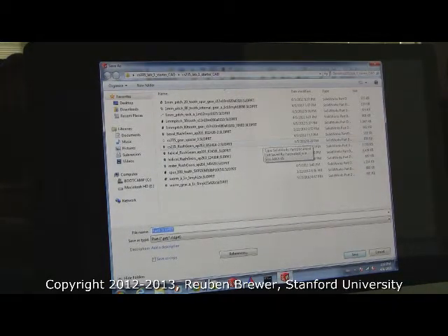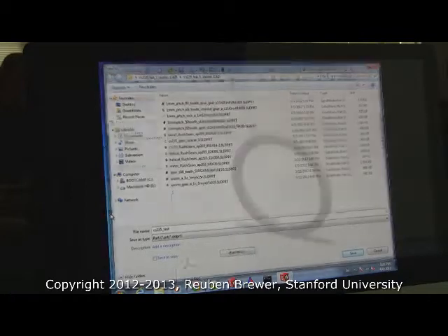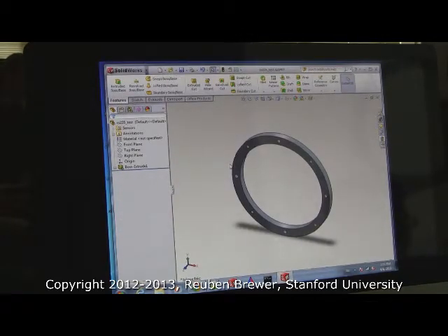Now it's very important. SolidWorks, for some reason, tries to save things in squirrely positions, like the temp files of Internet Explorer. I don't know why. Always make sure that you're saving it in the folder you think you are, because otherwise what will happen is you'll email me an assembly, but one of your parts will be somewhere random on your computer and I can't open it, but it opens perfectly fine on your computer because it knows all the random spots to put it. So how about just CS235 test? And you want to save frequently. After every major operation, save, because it will crash on you rather randomly.